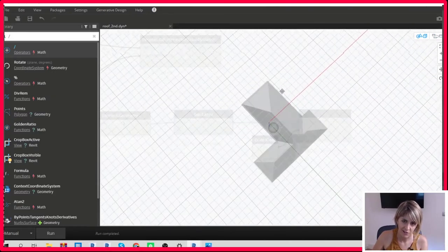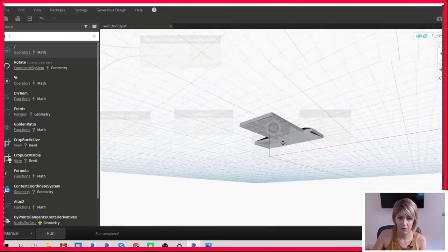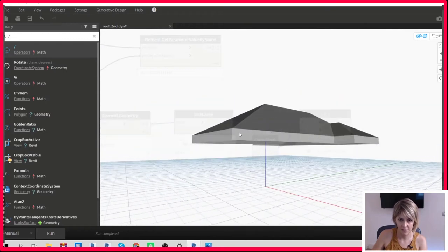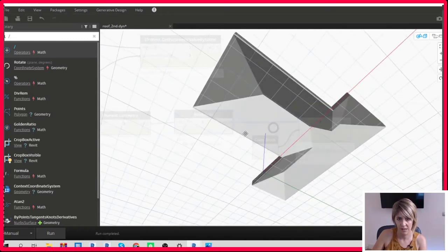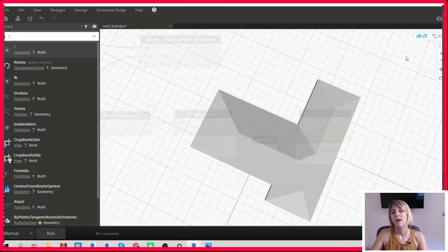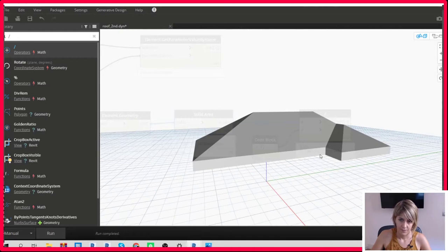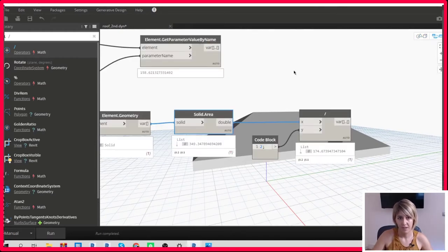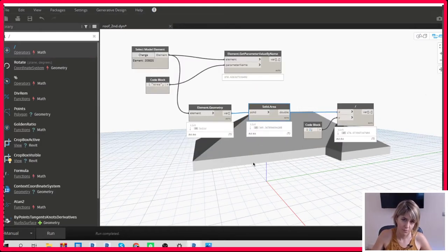So, even though this area really may correspond to the solid area, it can be that the surface is calculated per 2. Because if you notice, right here we have a thickness. This roof has a thickness. So it may be calculating this area and the other right here, as well as these vertical surfaces, and summing it all up. This is why if we divide by 2, this is quite similar, but we may have this to take into consideration.